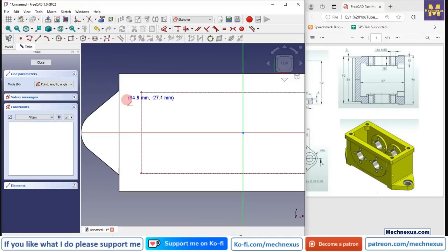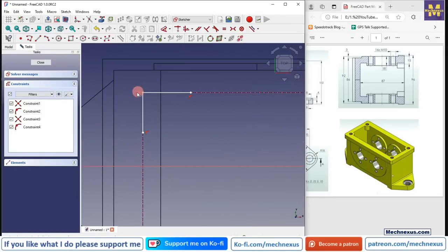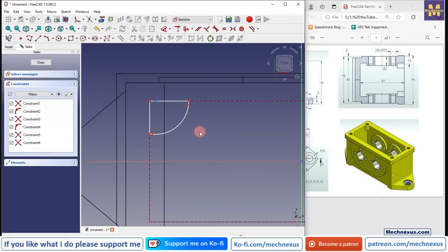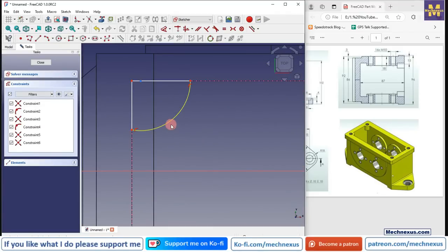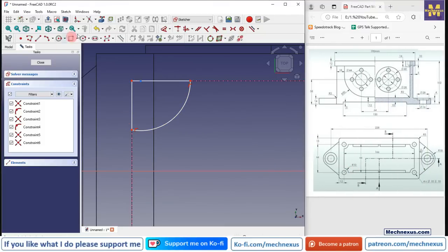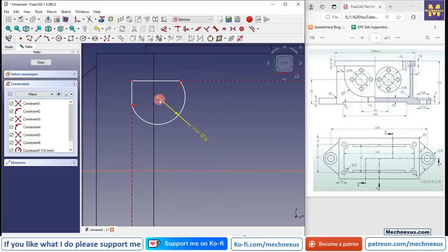we will select a line tool and switch to the wireframe, and here select a 3-point arc, and this is of a radius R10. We can see this dimension here. So first give the radius 10, select this and this, and add the coincidence relation.